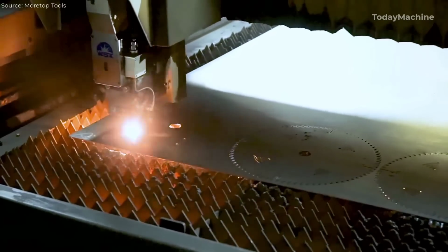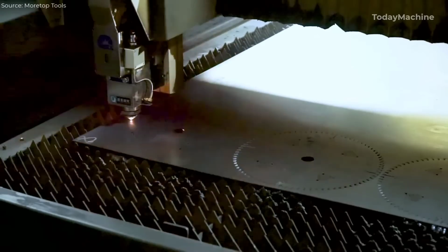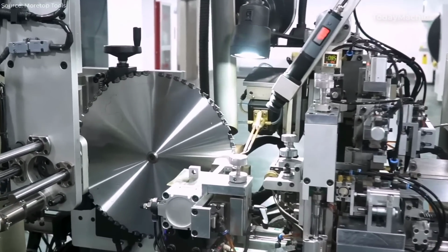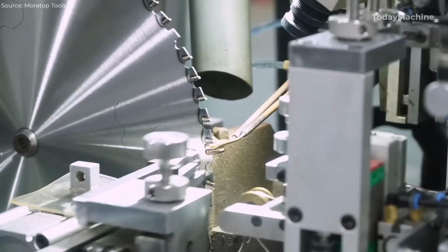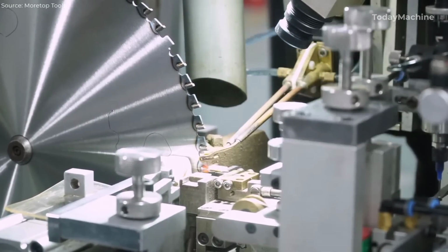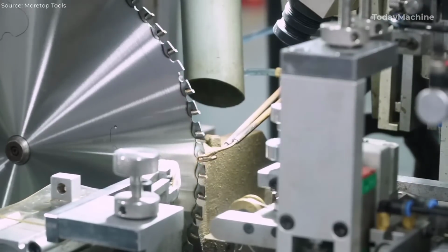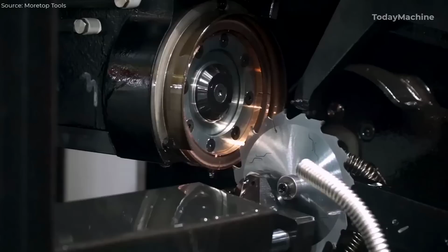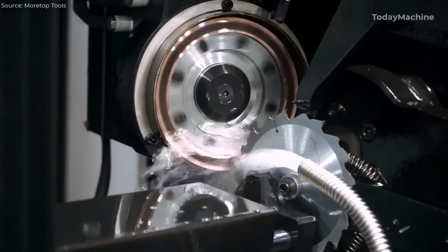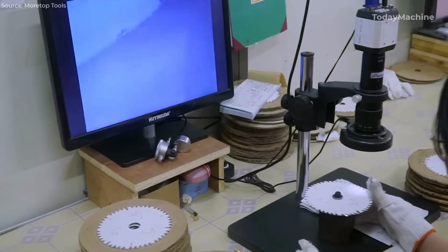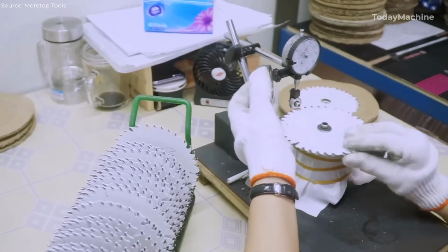Laser cutting and heat treatment. Laser cutting technology has revolutionized the production of circular saw blades by enabling more intricate designs and reducing material waste. Laser cut blades can have precisely cut expansion slots that reduce vibration during cutting, improving the blade's stability and extending its lifespan. Additionally, modern heat treatment processes have been refined to produce blades with a more uniform hardness distribution, enhancing their resistance to wear and fatigue. A high-quality circular saw blade can now achieve a Rockwell hardness of up to 62 HRC, making it suitable for cutting even the toughest materials.